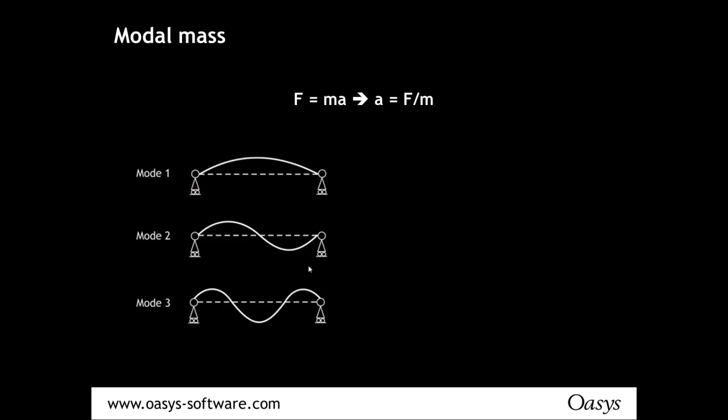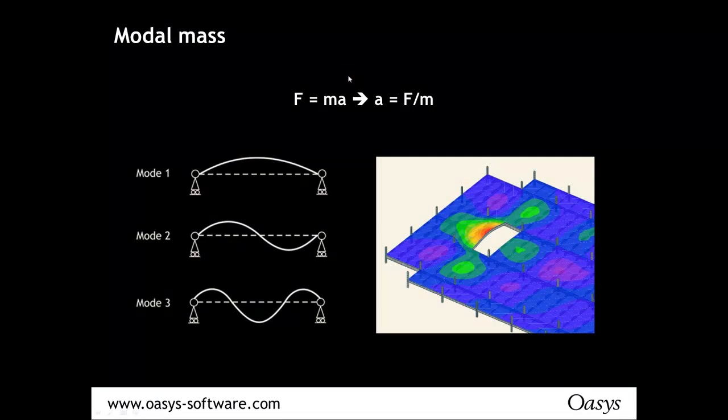And other modes, a similar sort of calculation. Now, because the force from the footfalls is constant, what we're looking for is accelerations. So, constant force, more mass, lower accelerations; less mass, higher accelerations, which means that you don't get a direct relationship between the floor vibration frequency and the response value.